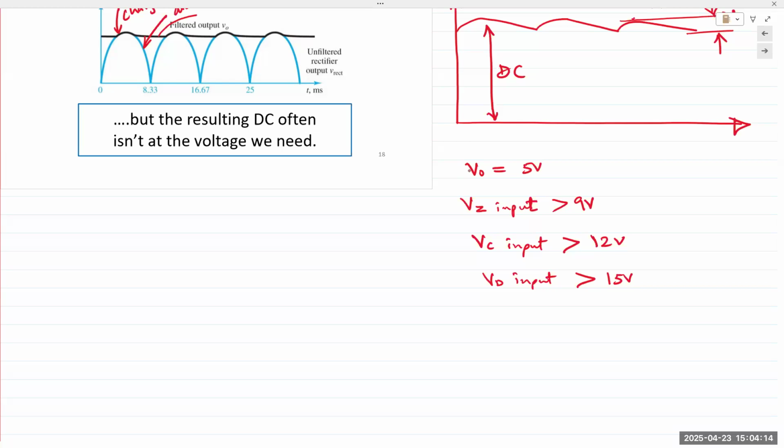Yes. So like in the power supply in the lab, when I turned the regulator. So the question being asked is, in the lab power supplies, those are complicated designs. So without looking at the internals, I don't know what we are actually changing. There are solid state controls. There's a device called an SCR, silicon controlled rectifier. There's another device called a triac. A triac provides a solid state device to control the output voltage. So depending on the design, it could be anything in there.